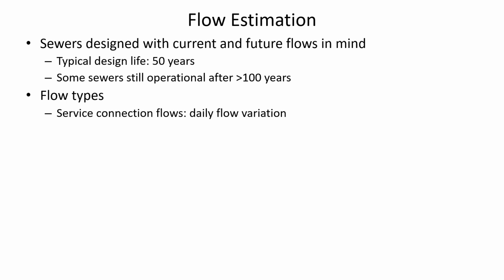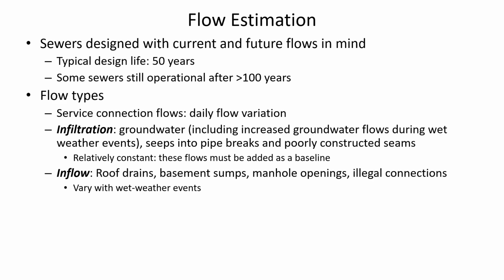And one of the things that's similar with wastewater pipe sizing as there was with drinking water pipe sizing is that there are variations in the flow from the middle of the night where the flows are low to the peak hours. There's going to be certain periods where a lot of wastewater is entering the system all at once. And there are complicating factors that we wouldn't see in drinking water pipe sizing. In drinking water pipe sizing, the flow demand is strictly determined by human use patterns.